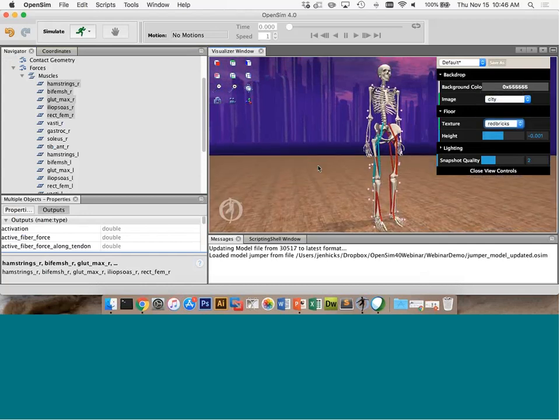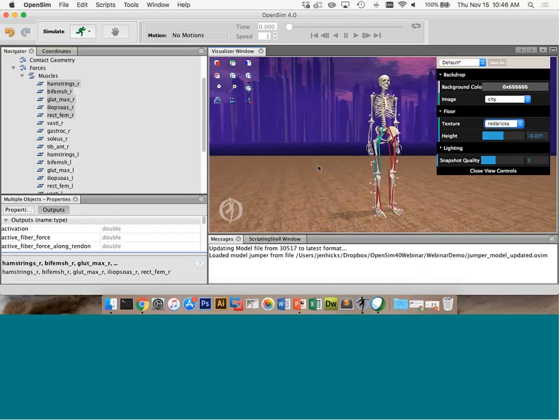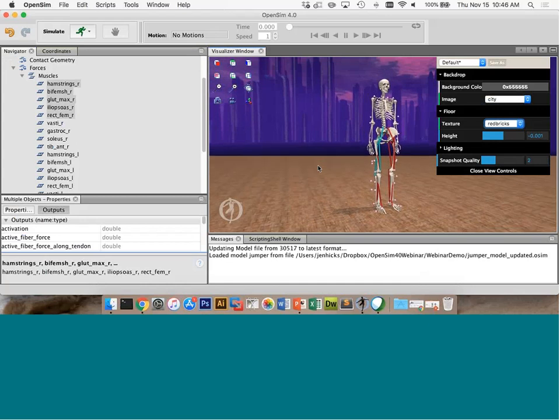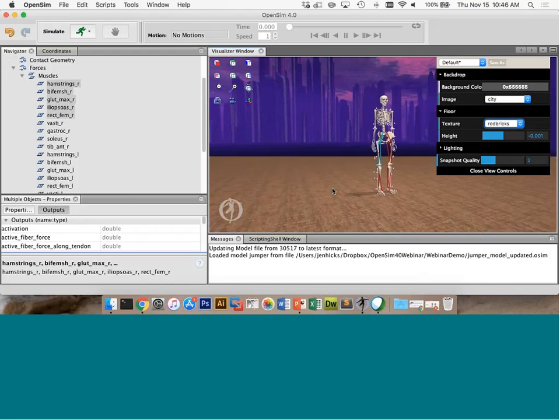And this looks more like a city, I guess. And you can also customize how the shadow is cast, because the shadow is a side effect of the lighting. So if I zoom out here and click on this scene lighting, I get a triad attached to the light source. By moving this around, I can position the shadow wherever I want, so it is behind the model or on one side rather than underneath the model.